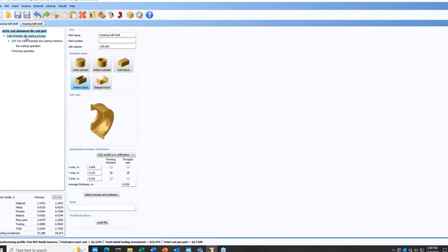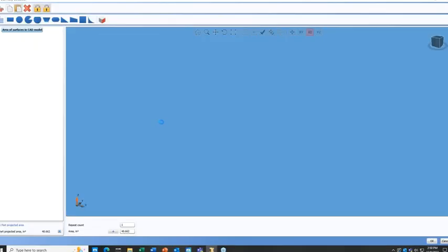So here on this first tab is our dynamic costing analysis of our die casting. You can see this is the analysis that we just completed together, and my cost result is the same, $2.71. Now I've created a copy of that analysis and specified all of the hidden information to see what kind of impact we have when dynamic costing is turned off. I've specified a batch size of 6,000 parts. I've accepted all of this information. My part volume has been brought over from my dynamic costing analysis. My part projected area, I've specified using the CAD model.